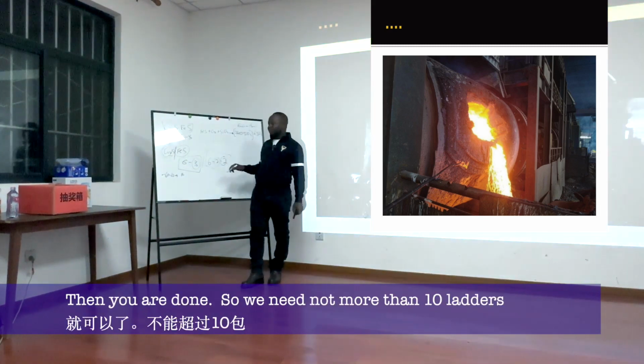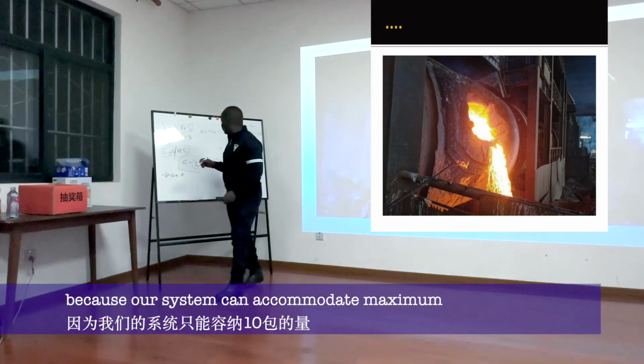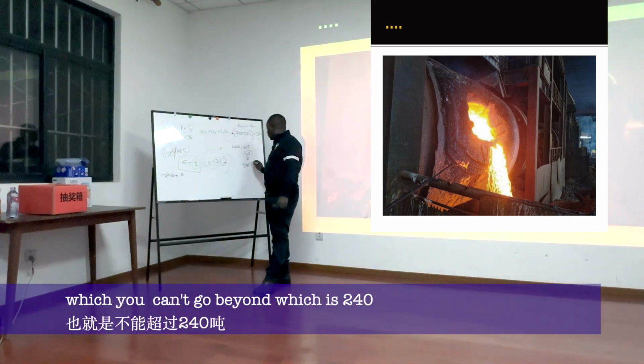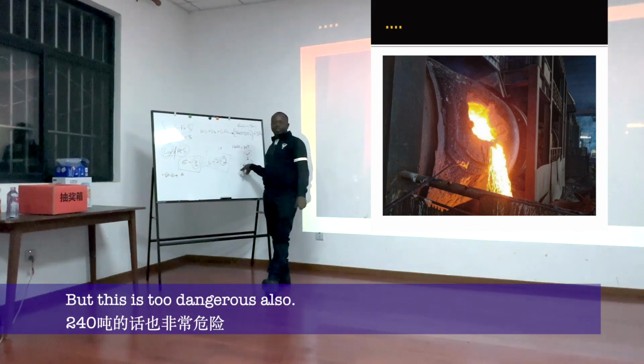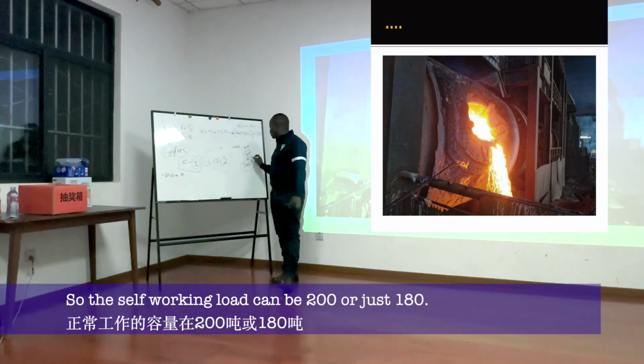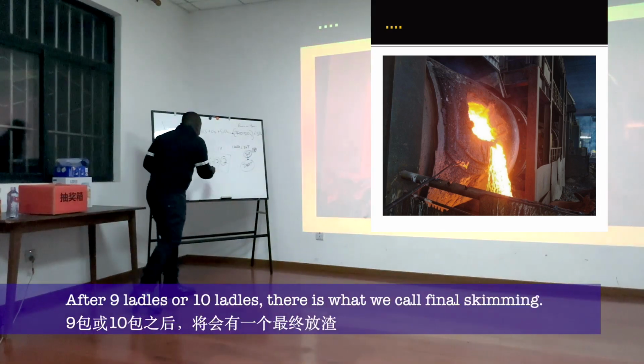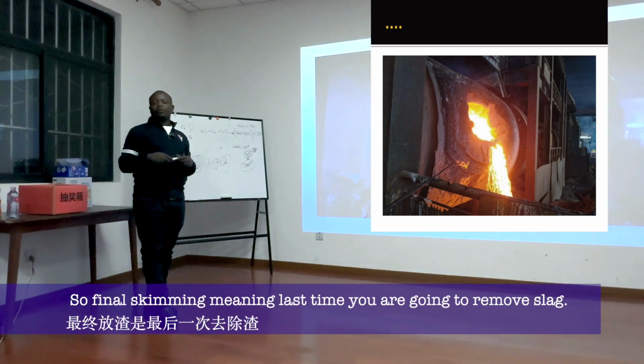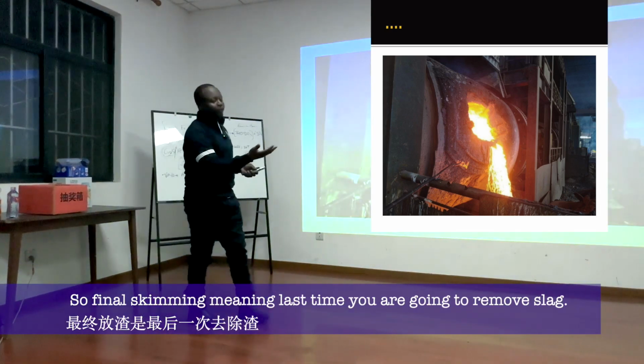Then you are done. So you need not more than 10 ladles, because our system can accommodate a maximum which you can't go beyond, which is 240. But this is too dangerous also. So the safe working load can be 200 or just 180. After 9 ladles or 10 ladles, there is what we call final skimming. So final skimming meaning last time you are going to remove slag.